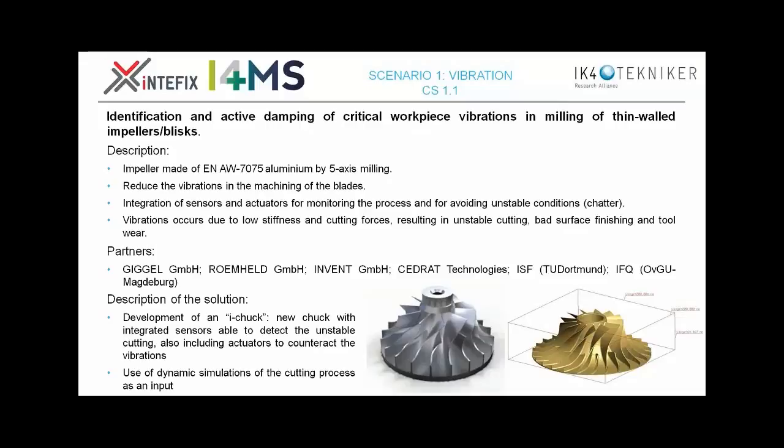So the idea is to monitor the fixture to be able to detect the vibrations and the unstable cutting conditions, mainly associated with chatter, and try to avoid these vibrations.